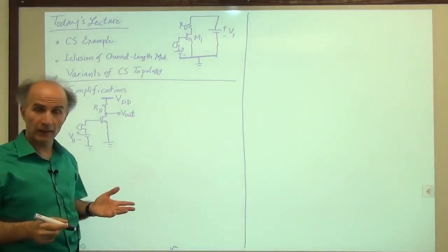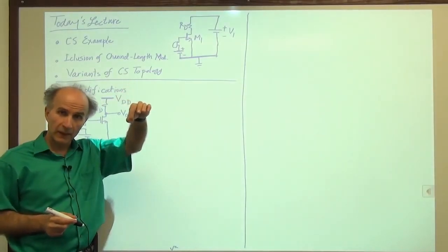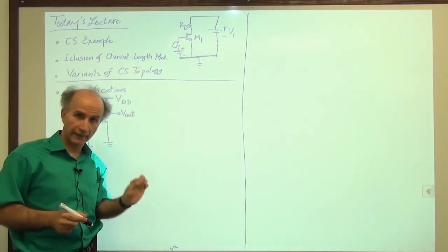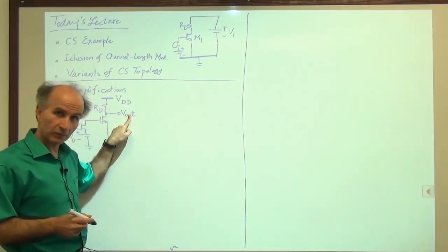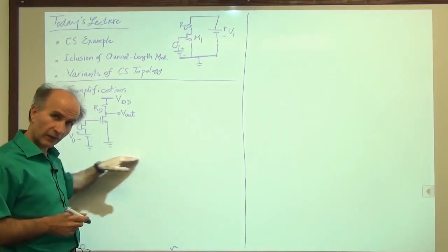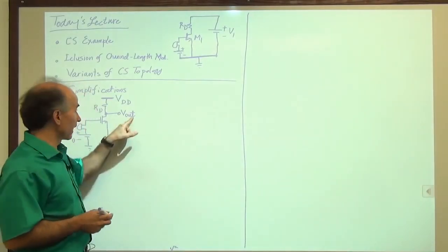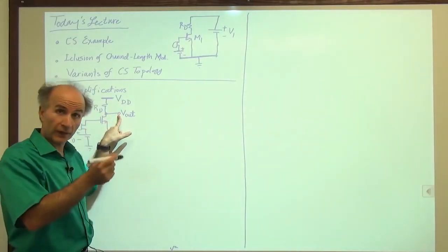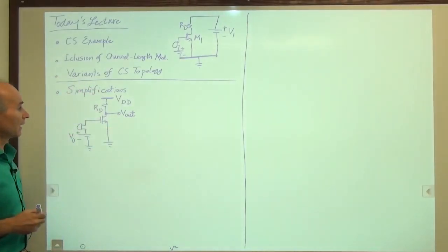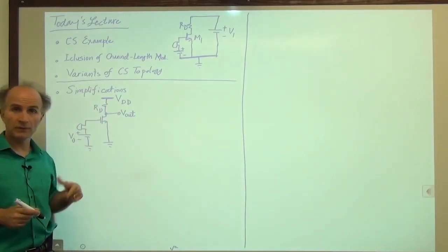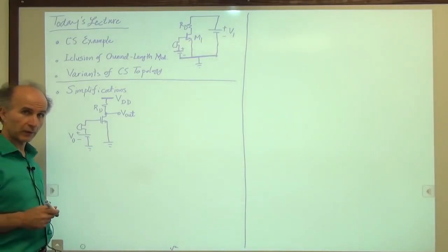That might be a little strange because we cannot associate a voltage to a node by itself. A voltage is always measured between one node and another node. But this just means that this V out is a voltage that is measured between this point and ground, this common rail here. But we just didn't draw it. That's all. So you should not assume that V out is one node with respect to nothing. It's always with respect to something. Okay, so that is the general simplified circuit that we will use from now on in our schematics, and I hope that you will not be confused by it.